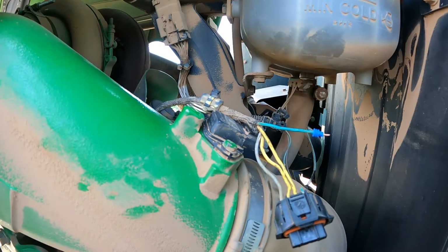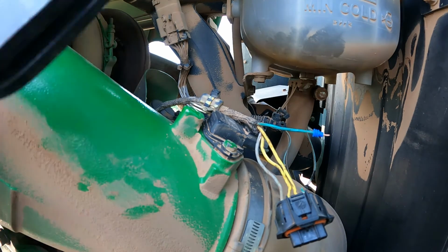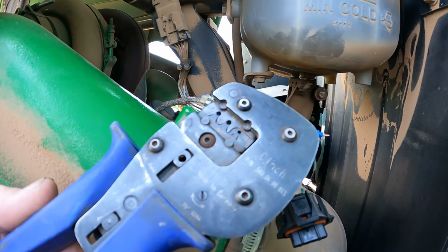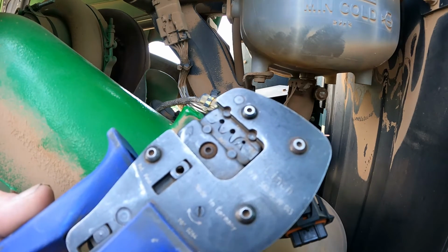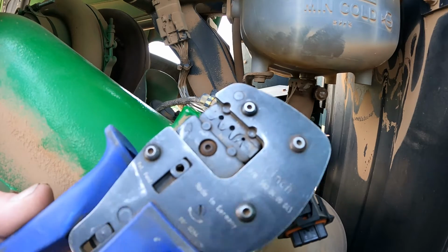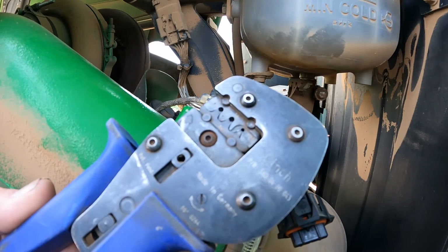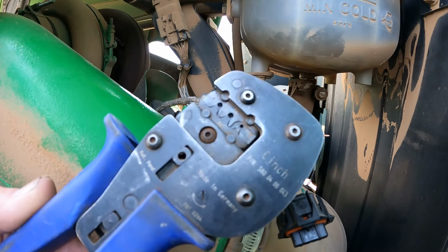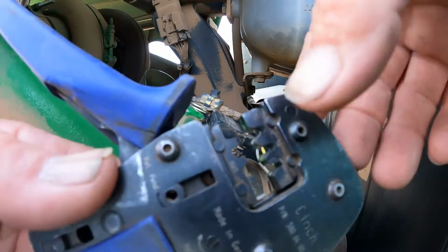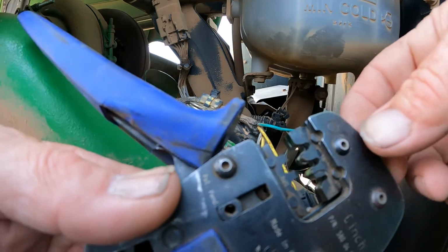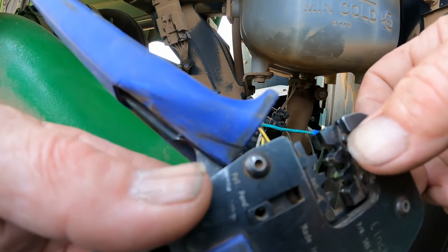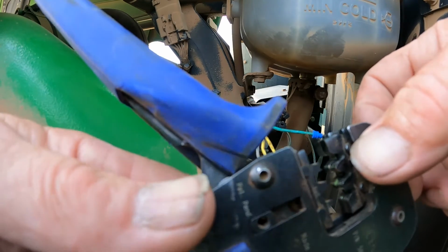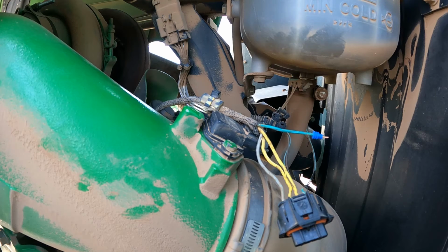So today I'm going to use a cinch style crimping tool that works really good even on that style of terminal. It's actually made for a different terminal, but it works really good on this style of a terminal. We're going to use the first portion here of the crimping tool. It's a little bit larger in diameter, and it crimps that terminal at just about the right strength. You can use various other crimping tools too, but this is the one that I like to use.